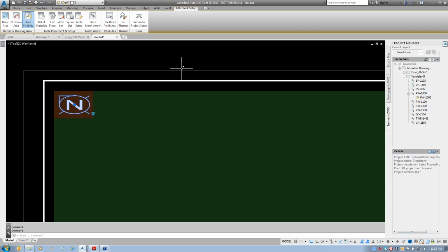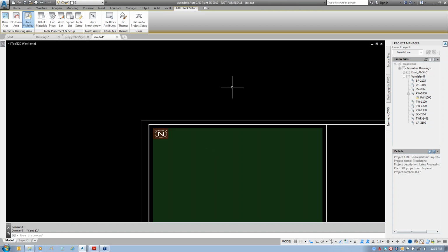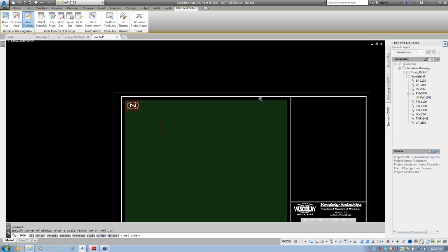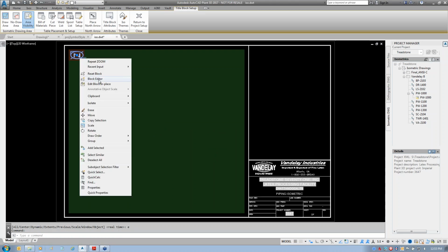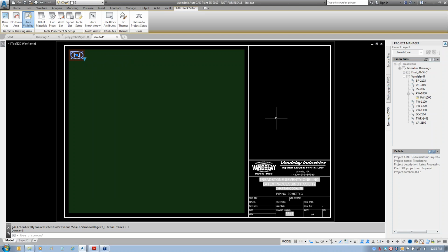So in this particular case, we're going to leave it there. You have to have all 4 visibility states for this to work correctly. So again, my suggestion is, if you want to change the appearance of how it looks, just go to the block editor at this point on that and make your changes there, and just make it look however you want it to.